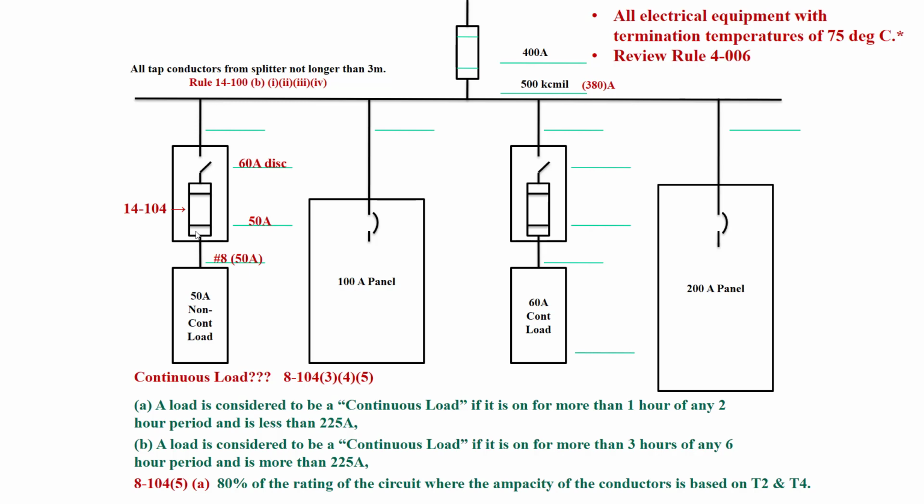Okay, so this rule here says that we have to particularly stay focused on that we needed to install this 60 amp fuse holder. So we have to size this wire based off the size. It has to at least cover the ampacity of the load. So number 8 for sure. But then the next part is that it has to be at least the ampacity of that fusible disconnect.